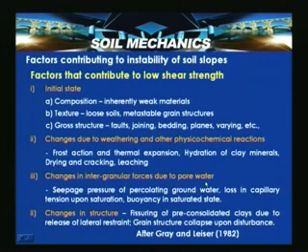And changes in intergranular forces due to pore water pressure, seepage pressure of percolating groundwater, loss in capillary tension upon saturation, buoyancy in saturated state. These factors can contribute to a low shear strength. Another one is changes in structure like fissuring of preconsolidated clays due to release of lateral restraint, and grain structure collapse upon disturbance. So, what we have seen is that the factors that contribute to the low shear strength are the initial state, particularly composition, texture and gross structure, faulting and dipping, changes due to weathering and other physico-chemical reactions, changes in intergranular forces due to pore water, and changes in structure. And these factors can contribute to the instability of a soil slope.